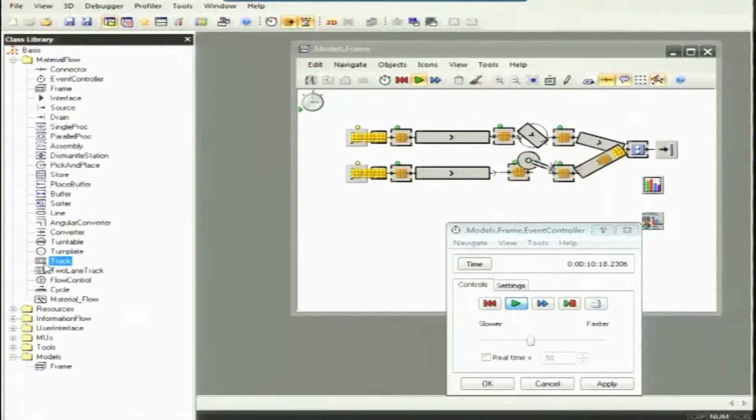The track's length can be defined, then the transporter's mobile unit length can be defined, and the speed can be defined. So the maximum capacity of the track is defined by its length and the lengths of the individual transporters moving on it. That is, a track that is 3 meters long accepts 3 transporters of 1 meter each. So there can be certain other capacities.